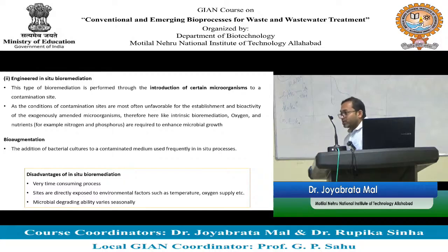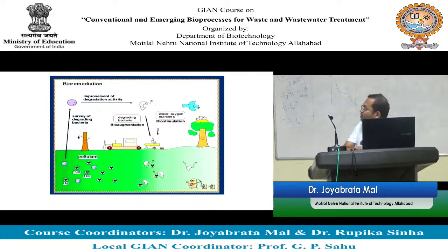So you can specifically design some microbes and add them into the sediment or soil to remediate it. But one thing is, when you are adding microbes, it always has to be combined with biostimulation. Because you are adding specific microorganisms, they also need specific conditions, right? So in engineered in situ bioremediation, you always have to combine bioaugmentation and biostimulation to provide the best possible atmosphere for the added microorganisms.